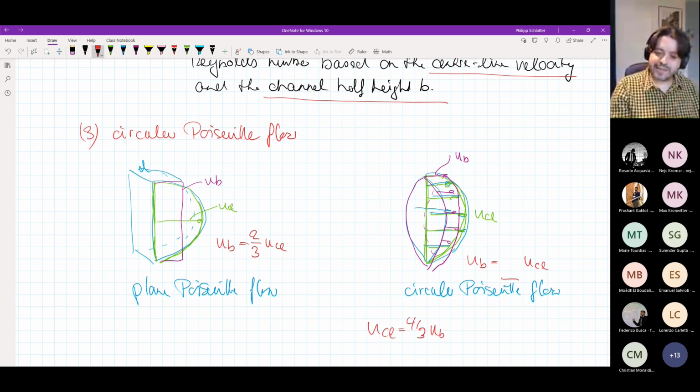Which of course means now that the correct result is unfortunately exactly the one that got the least amount of votes, which is that the centerline velocity in a pipe is actually faster than in a channel to obtain the same bulk velocity, because the area of the center region is lower. So the correct result for this equation would be actually 1/2 of UCL.